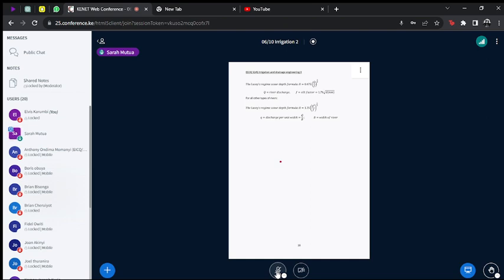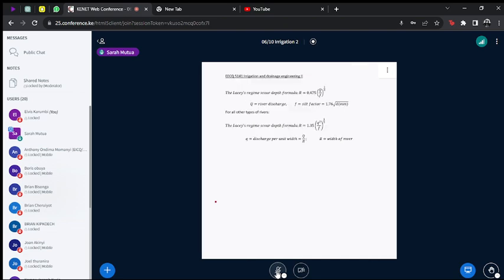How do you determine that? Bligh's theory will help you determine the depth of the other piles because you have to make the creep length as long as possible. Once you have done that with Bligh's theory, then use Khosla's theory to check pressures, and then adjust your system appropriately. So this is the method of independent variables.